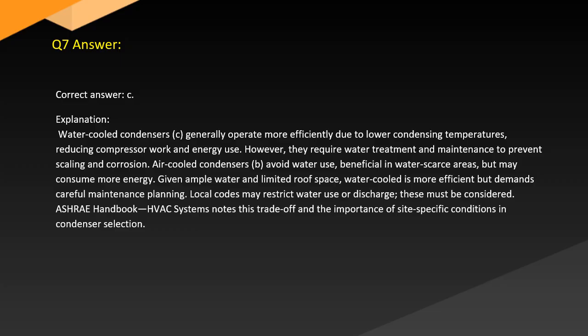Given ample water and limited roof space, water-cooled is more efficient but demands careful maintenance planning. Local codes may restrict water use or discharge. These must be considered. The ASHRAE Handbook, HVAC Systems, notes this trade-off and the importance of site-specific conditions in condenser selection.